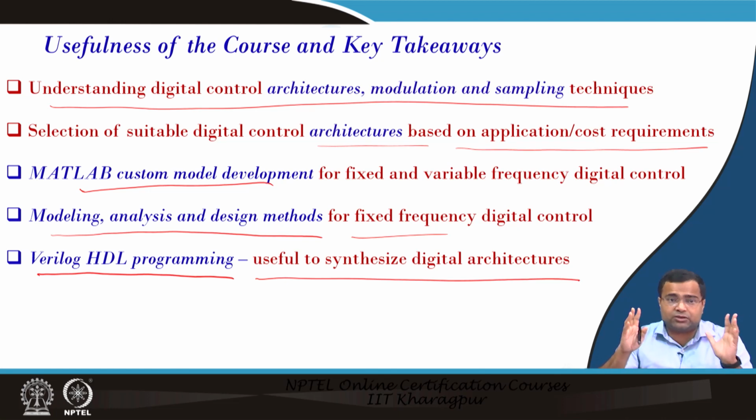So that means the best way to write Verilog code is first to draw the circuit, understand the concept, draw the circuit, then try to write the Verilog using structural or dataflow modeling, and as much as possible avoid behavioral modeling. Instead of writing full algorithm level, we should implement the circuit level thing in Verilog.